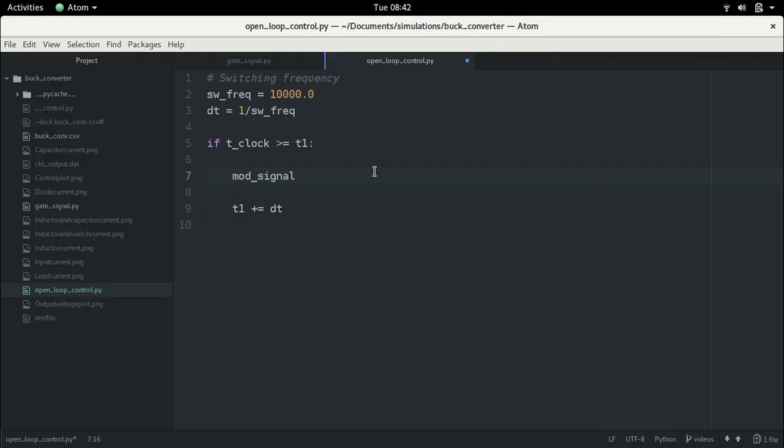So what we're going to do here, again, really speaking, you would need to implement a PI controller or some other form of controller. There are many other forms of controller. If you want to look at advanced controllers, there is deadbeat controller, there is pole shift controller, there is several others. Or you can even look at something like proportional resonant controller. It's a very vast topic, I won't talk about it. What I'm going to do here is I'm going to do a very simple concept of just incrementing the modulation signal from its existing value. So I'm ramping it up from 0 to some value, right?